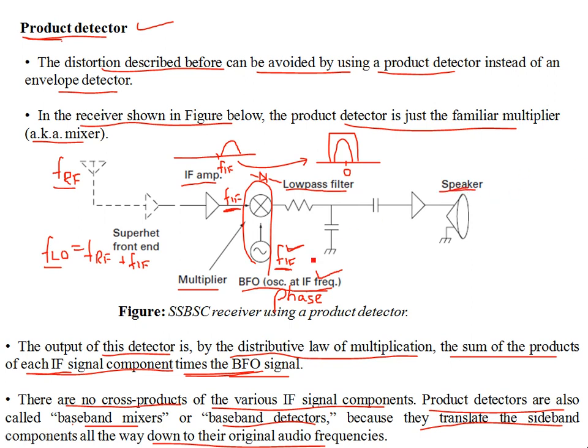Okay, even if the phase is a little offset, it's still intelligible what you're going to listen to. But for correct amplitude and to avoid any phase distortion, it's convenient to have a small pilot signal that can be transmitted from the transmitter, and this information can be given at the receiver. So the BFO locks to the correct phase. Okay, that is important. If it locks to the correct phase, the amplitude of the original audio is the same at the output.